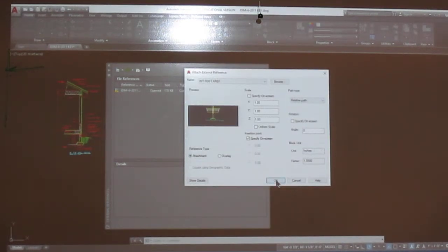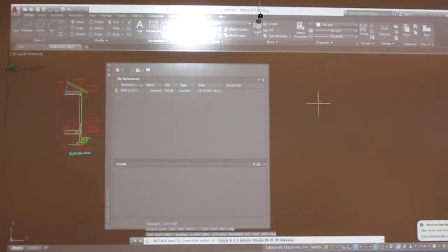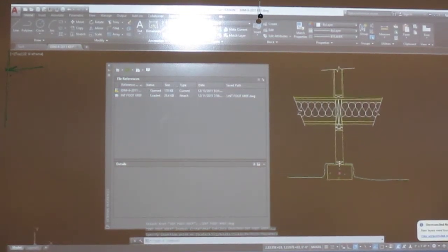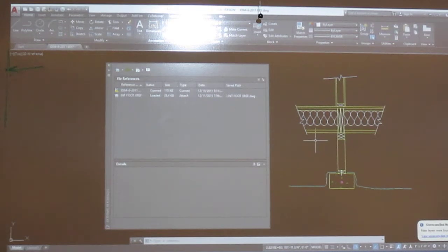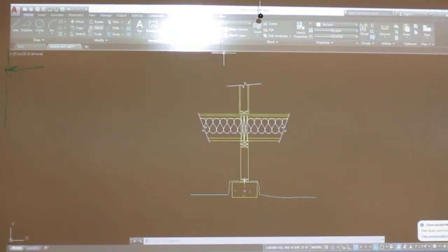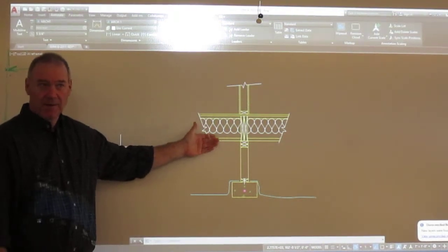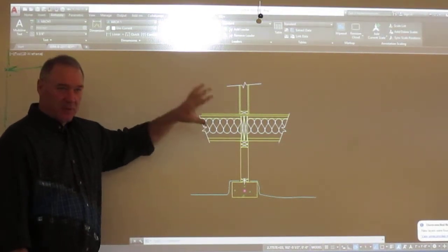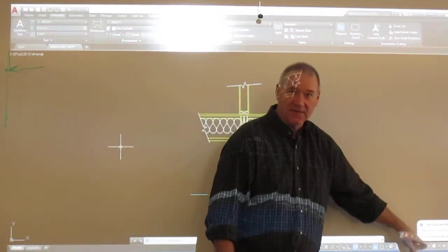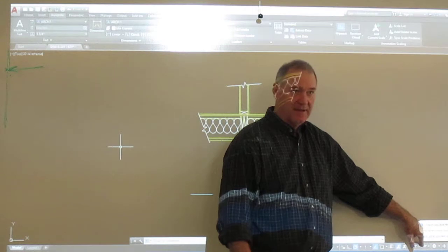Again, just drop it in at scale 1:1. And I just want to drop it somewhere in my drawing where the space is all alone, so you're going to be sitting with this type of drawing now. Now, the only thing you'll have to do here is annotate it, because it's 1:1. So you say, okay, what scale am I going to print this at? In this case, you're told we want to do it 1 inch to a foot. So the only thing I need to do here is place this in, set my annotation scale to the one I'm going to plot it at.